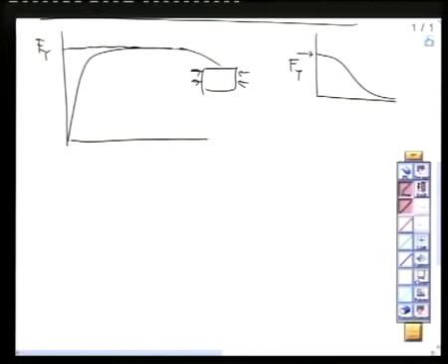The member which can deal with such deformation is called compact. The member that reaches Fy and then goes down is called non-compact. And finally, any member that does not reach Fy is called slender. In columns, we need either compact or what? Or non-compact. And for non-compact limitations, we took that